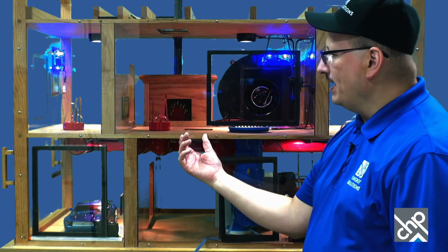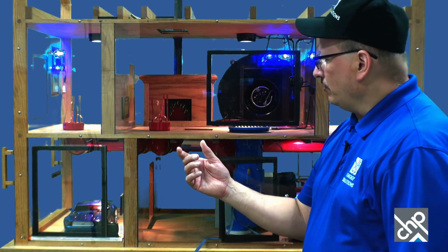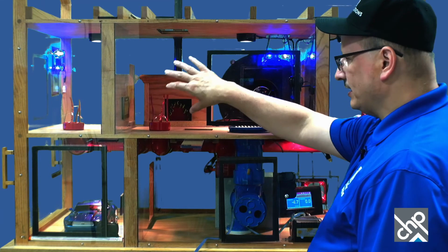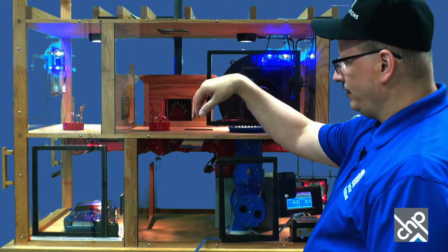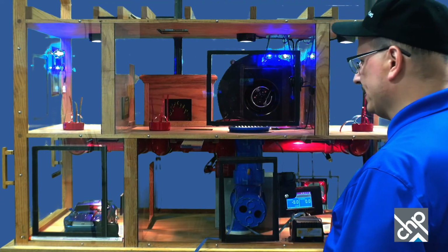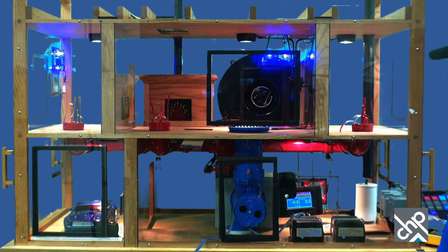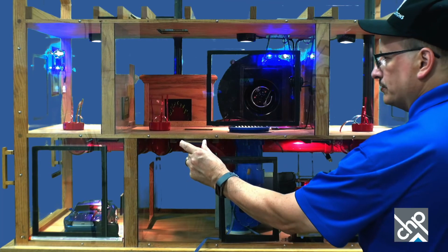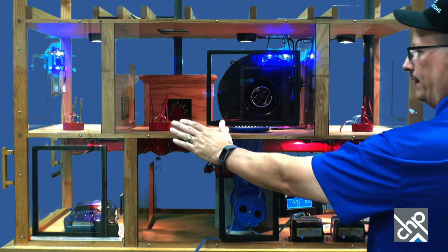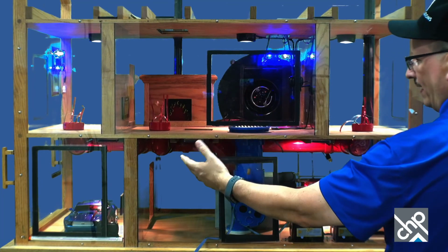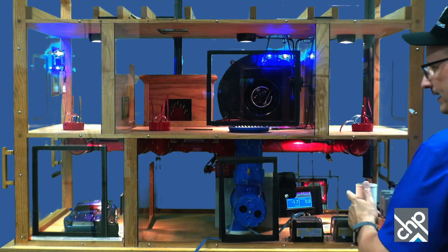It got better when we closed the door because when the door is open, this central return can suck from this space, pulling from this living room area and from this basement CAZ. When we were around minus 4 point something, like we had before, 4.8. And then when I close this off, that isolates that return up here. It's not sucking from the basement anymore, not very much anyway. And now the CAZ actually got better.